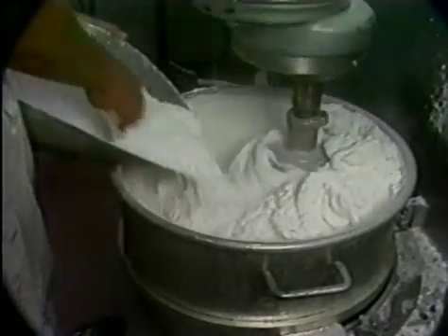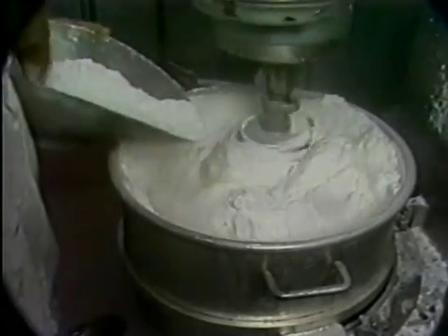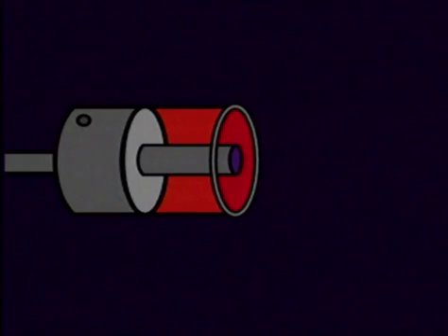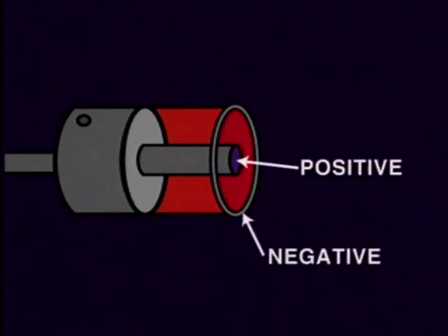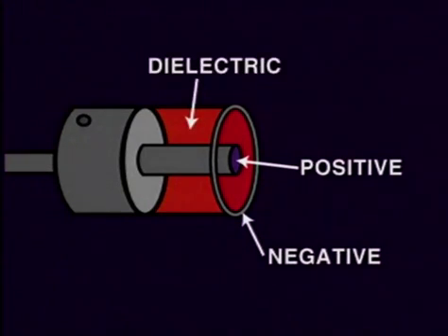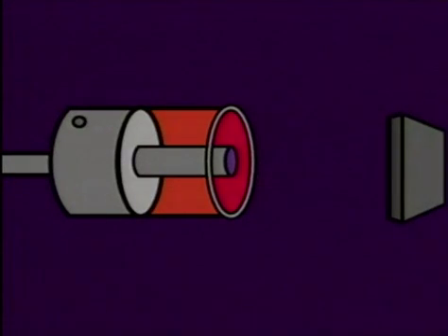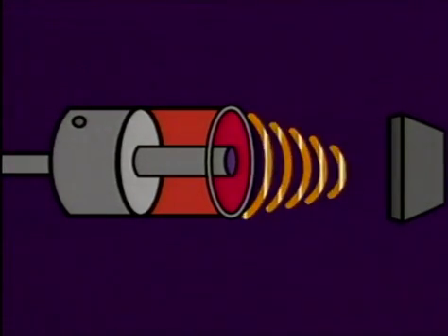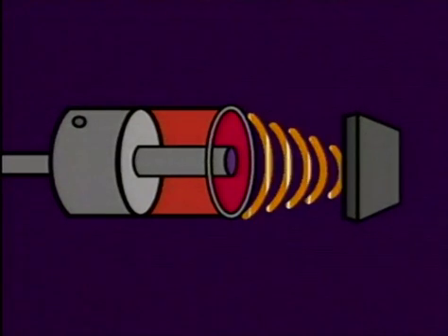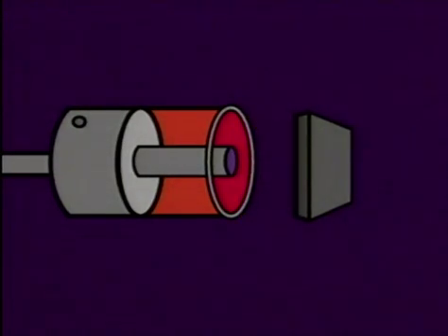Capacitive proximity switches can be used to detect all materials and are suitable in the detection of fluids and granulars. The capacitive switch operates in a similar fashion as the inductive type, except that the oscillating circuit uses one positive and one negative capacitor plate, separated by a poor conductor called a dielectric. When power is applied, a high-frequency field is created similar to that of the inductive switch. Any changes in the dielectric field outside of the sensor would be detected, and the switch would react by changing states to its contact output.